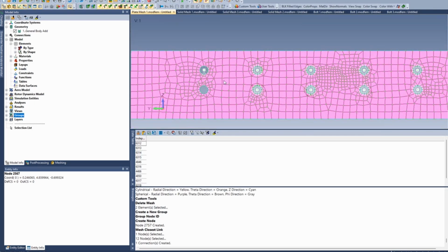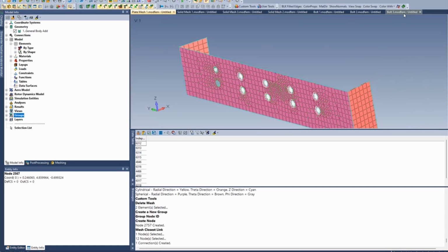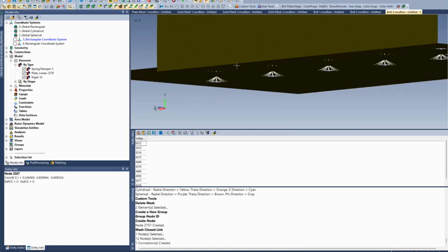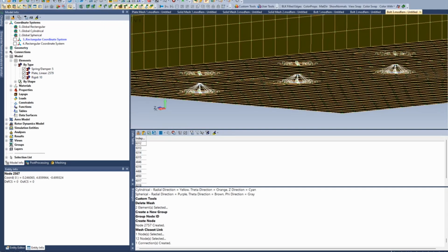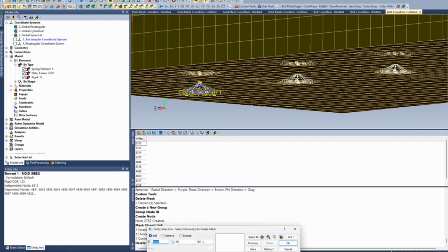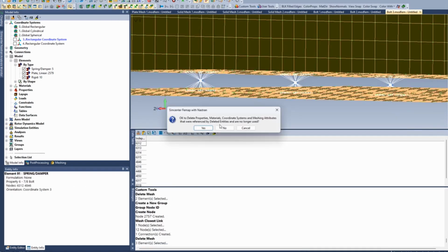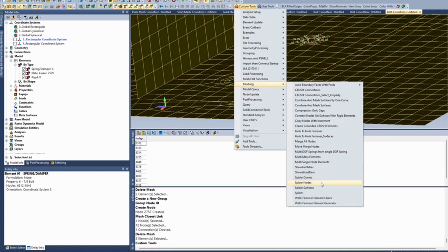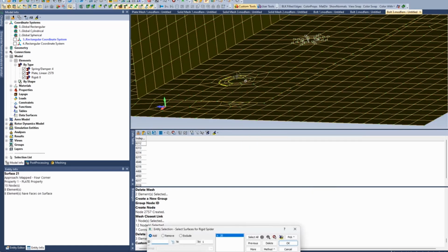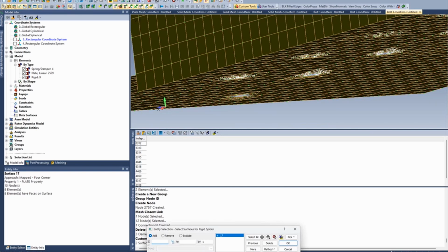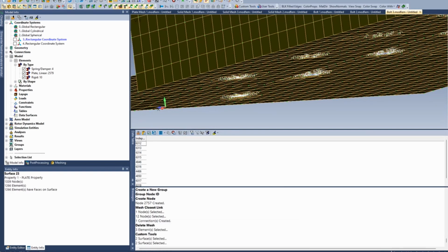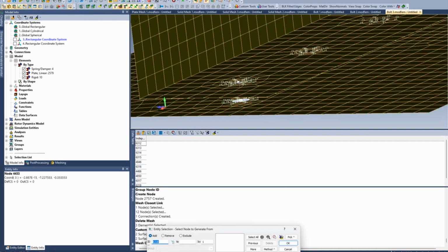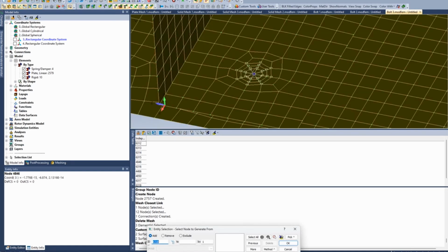So if I created two CBUSHs here and used mesh connect closest link, I think that would probably be about the same as using the coincident link.